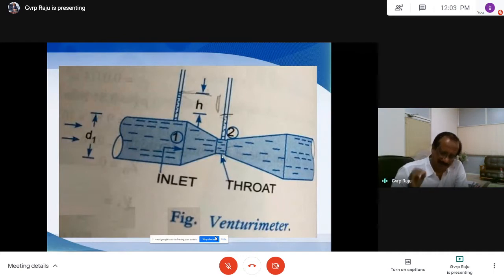As you know, vapor pressure is the pressure created by vapor due to accumulation of vapor bubbles when the top of the container is closed. We have discussed that in the first chapter. So when the pressure at 2 is less than the vapor pressure, what happens? There will be vaporization, which results in cavitation. These are important objective type questions. Number of times they ask about cavitation. Cavitation is a formation of vapor and air pockets.